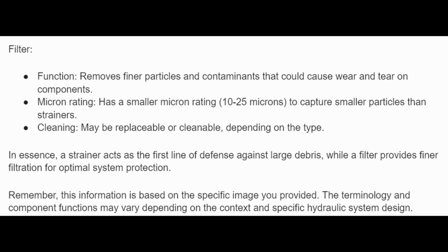A filter. Its function is to remove finer particles and contaminants that could cause wear and tear on components. It has a smaller micron rating, 10 to 25 microns, to capture smaller particles than strainers. Cleaning. May be replaceable or cleanable, depending on the type. In essence, a strainer acts as the first line of defense against large debris, while a filter provides finer filtration for optimal system protection.